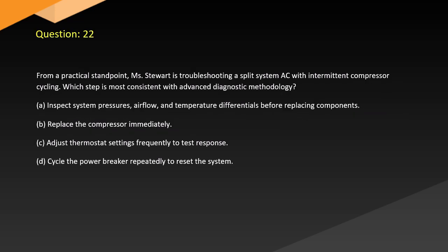Question 22. From a practical standpoint, Stewart is troubleshooting a split system AC with intermittent compressor cycling. Which step is most consistent with advanced diagnostic methodology? A. Inspect system pressures, airflow, and temperature differentials before replacing components. B. Replace the compressor immediately. C. Adjust thermostat settings frequently to test response. D. Cycle the power breaker repeatedly to reset the system.